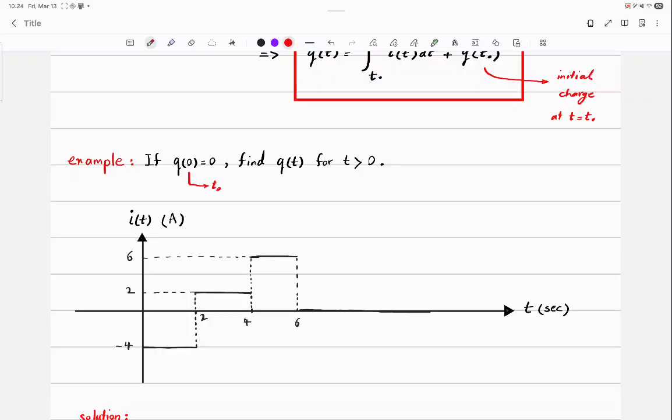When I'm talking about current entering voltage in the previous page, current entering from the positive terminal of voltage, do I care what is the value of I and V? No. I only care about multiplying I and V, whatever value they have. They might be both positive, they might be both negative, whatever. If you multiply I and V in this way, when current is entering the positive terminal, the value that you find is absorbed.